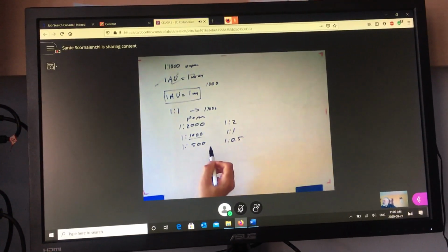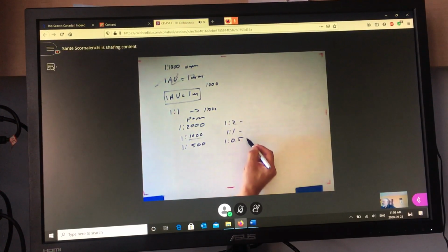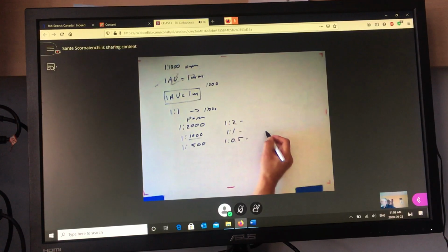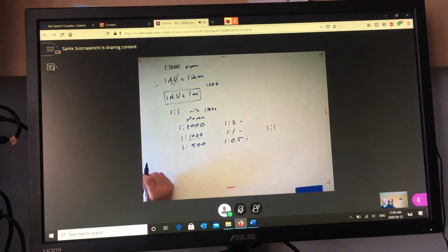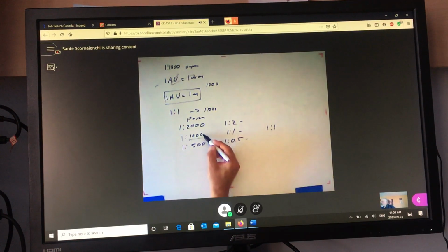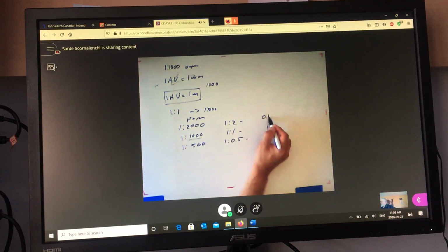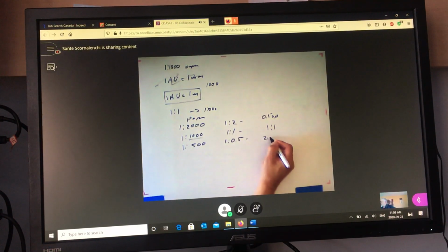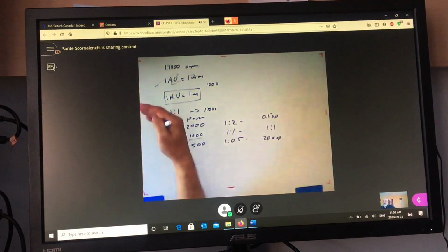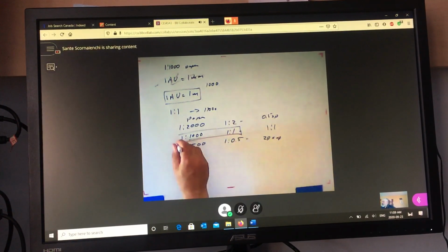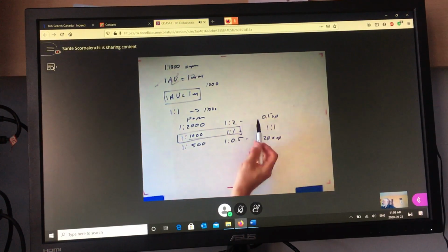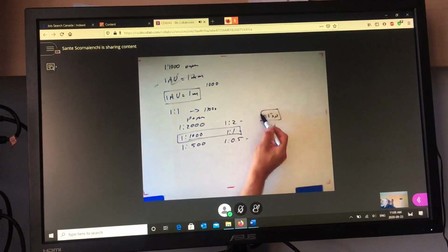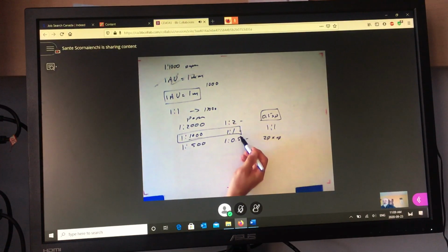We're not going to do that. What we're going to do is, instead of plotting at these different numbers, we're always going to plot at 1 to 1. And then we'll change the zoom factor on that window I drew, right? So if I want to go from 1,000 to 2,000, I'm going to make my view half of model space, 0.5 paper space. If I want 1 to 500, I'm going to use a factor of 2 times XP, or paper space. Okay, so I'm going to change my zoom factor and always plot at 1 to 1. So on paper, we plot at 1 to 1, and then we change the zoom factor. If I want 2,000, I change this scale of the zoom factor to half. If I want 1 to 500, I make it twice as big.